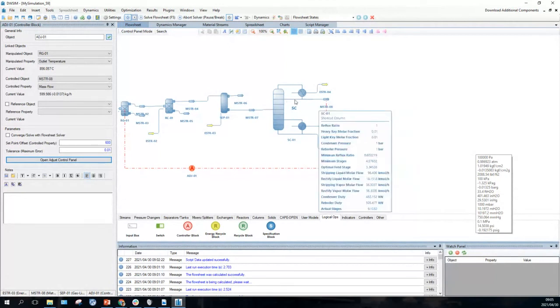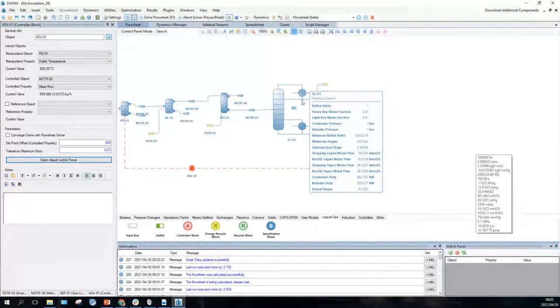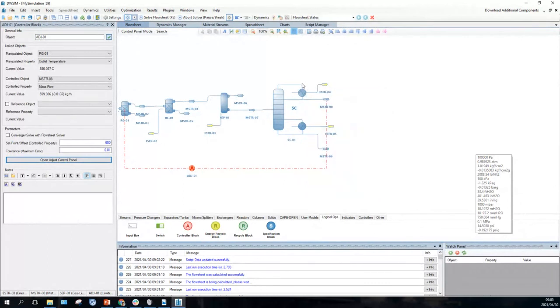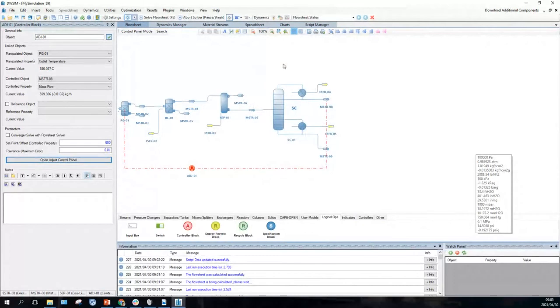But normally on a process flow diagram, you would show the gas stream coming off that way, and you'd show the liquid stream splitting down here. So this would typically only be a liquid stream. And those vapors you would mix with these vapors, and then we put in an absorber. Let's go back to the columns. We put in an absorption column so that we can put in water to strip out the last of the methanol.